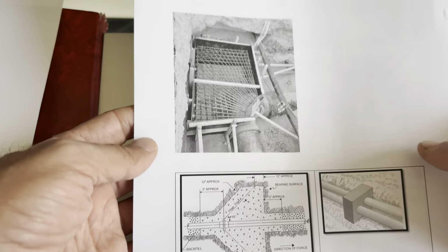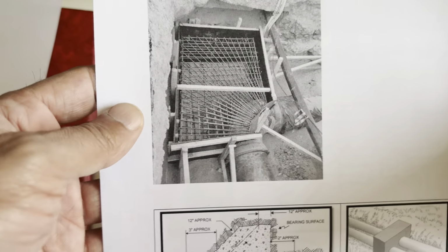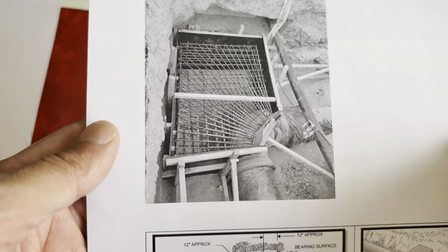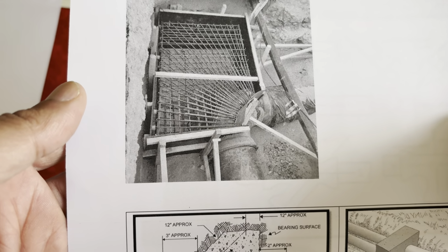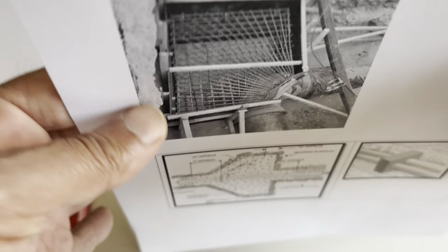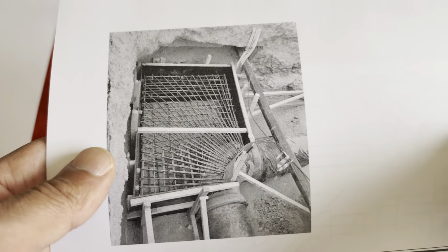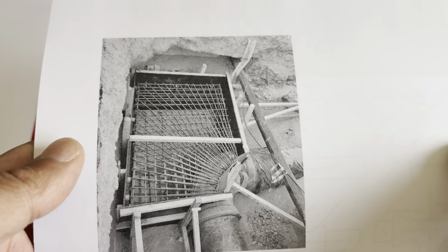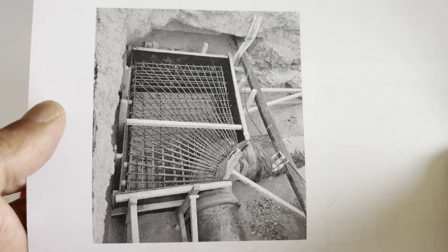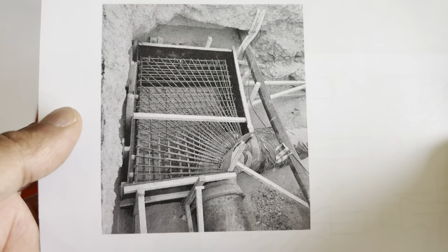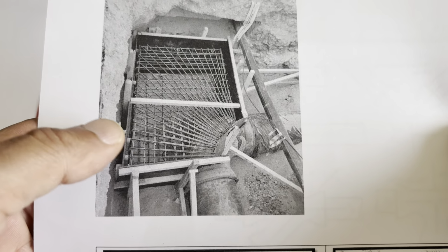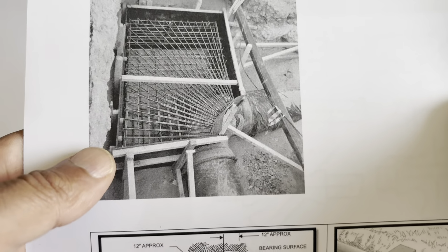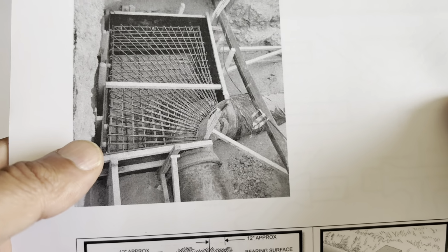In general, we do thrust blocks without reinforcing. I will say why, but remember, it is an unwritten principle for all designers, because the designers for this piping system are always mechanical or process people, but the thrust block design is something structural, and we need to take care about this. In general, everyone believes that a thrust block, especially in a normal bend, T-section or dead end, should be unreinforced. But still it depends. It may need reinforcement or it may not.